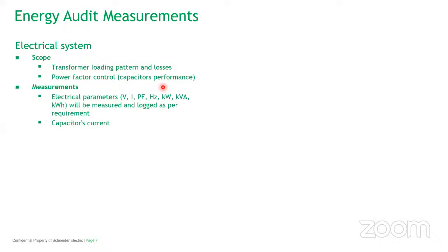Okay, so these are the three types of power normally monitored at the transformer level. Ideally, the apparent power and your active power should be almost equal. That means your power factor plays a very important role. You should maintain unity power factor as near as possible, like 0.99. Okay, so we need to see what the power factor level is.